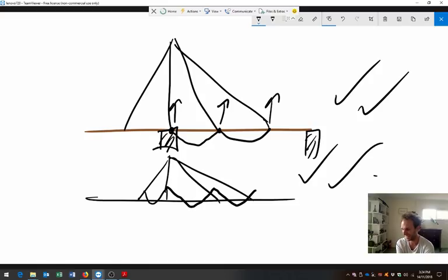Joe, this question concerns me a little bit because it shows that you don't necessarily get the difference between a CFA and a bored pile. A bored pile, we're ending up with an open hole in the ground, so we can just drop the rebar in as deep as we need to. The CFA pile, we're ending up with a hole in the ground full of concrete, so we just can't force the reinforcement cage into that concrete very deep.